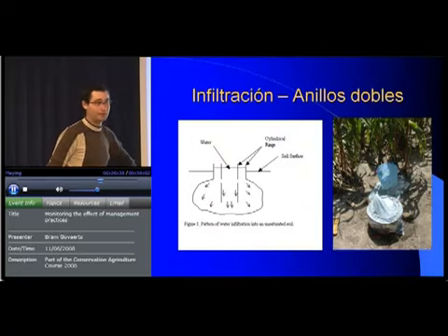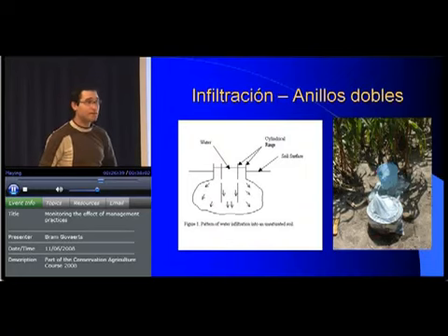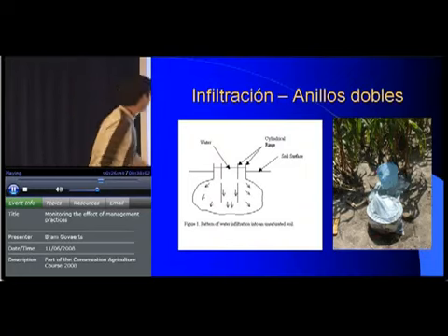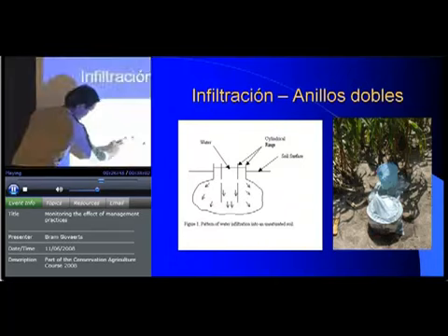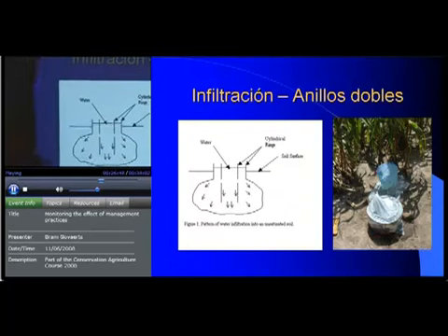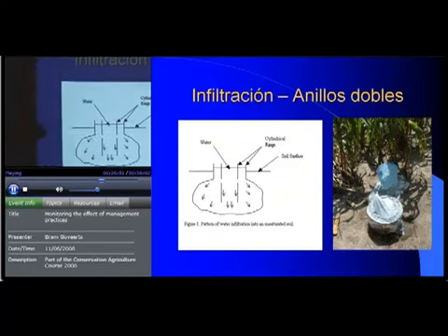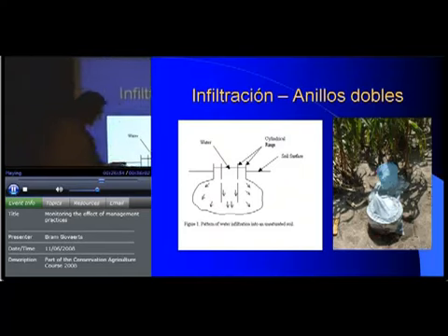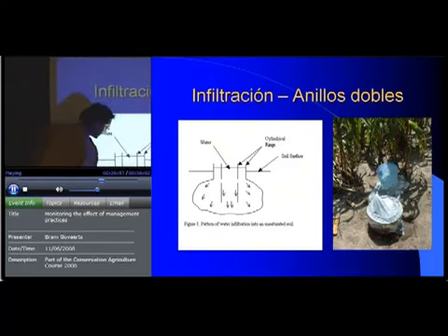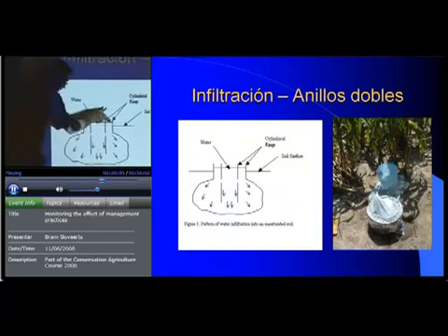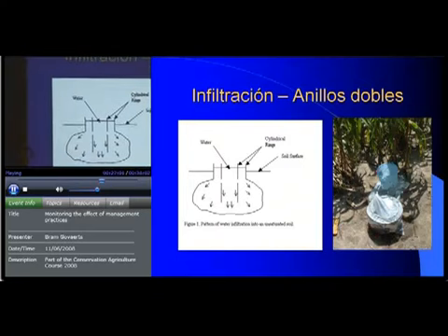in practice, right? And what they also give you is saturated infiltration. That's why you have a double ring. You have a double ring because you're measuring this flow. And you're putting water in the second ring, well, between the first and the second ring, because you want to wet this front, because you want to avoid this water running that way, right?